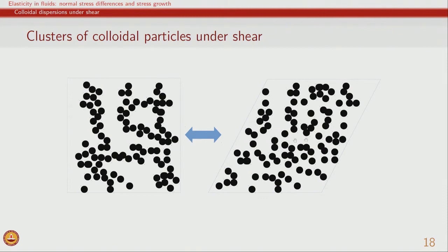But if the system is sheared, for example the top surface is moving at a higher velocity compared to, let us say, the bottom plate which is stationary, then some of these particles are being forced to move at a different velocity compared to the others, and that will eventually lead to cluster breakage, and therefore much smaller sizes of cluster, and also there is no percolation, and clearly in this case viscosity will be much lower. And so, we discussed this qualitative picture while we were looking at the shear thinning nature of many of the colloidal dispersions.